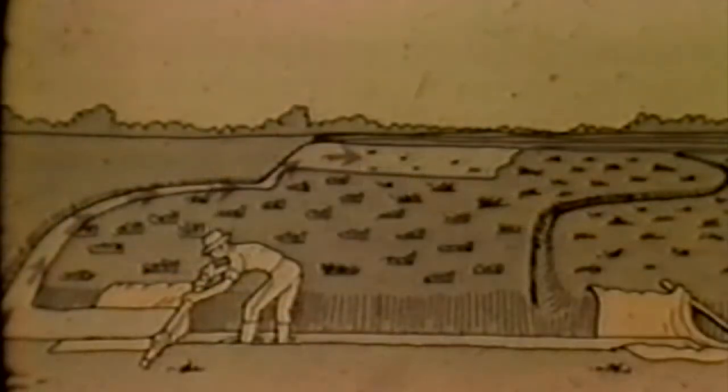The contour ditch type of surface system is laid out on sloping land after the crop is planted. When irrigating, a temporary dam is made in the head ditch just below the contour ditch. The water in the contour ditch is also checked by a temporary dam. Water then flows around the slope in the contour ditch on the upper side of the strip to be irrigated. And as the water rises in the contour ditch, it floods over into the strip below.